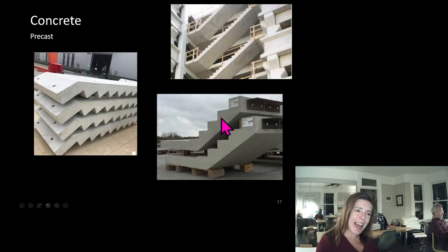I've seen cast in place stairs in steel buildings. It's not as common, simply because the advantage of precast is that you can bring it in later and install it. But if it's inside the building, how do you actually get it in? Because if it's a steel stair, you can bring it in pieces and assemble it in place. Stairs are often the last part of the project. In the short term, they usually build a rickety wood temporary stair.